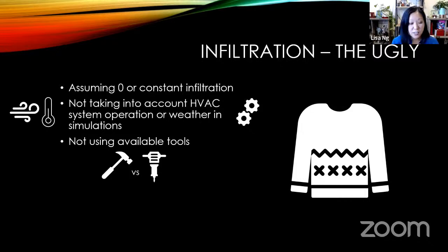Another one is not taking into account HVAC operation. You'll see from that video that I linked up earlier that it's going to really depend on what parts of the building are pressurized or oversupplied, whereas other building locations are underpressurized or depressurized because of exhaust fans or other things happening in the building. And then not using the available tools.